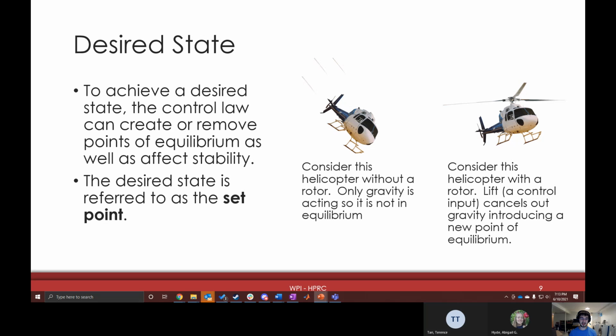But it's a lot harder without any acceleration. Typically, that would require finding your position relative to something else. And from there you can see if your position is changing relative to that thing, and you can do that in a lot of different ways. One very basic way is using an ultrasonic sensor, which basically sends out, that's like how a bat senses things. Have you ever seen those Arduino ultrasonic sensors? Kind of looks like two little speakers. Yeah. Basically that emits a sound wave, and it listens for the return, and it's able to tell how far away some object is, and that gets your position in one dimension, basically.